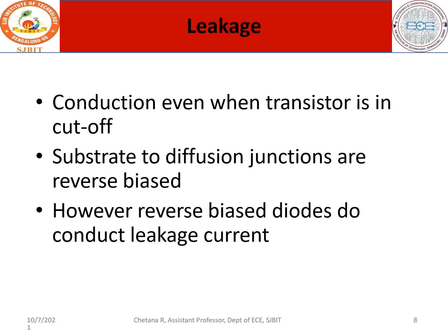However, reverse biased diodes do conduct leakage current. So whether it is forward biased or reverse biased, there is a leakage current, and this has to be avoided. In order to avoid this, in the substrate we add an extra layer called the epitaxial layer. The epitaxial layer, to one extent, reduces the junctions being formed and breaks them, and as a result leakage current is avoided.